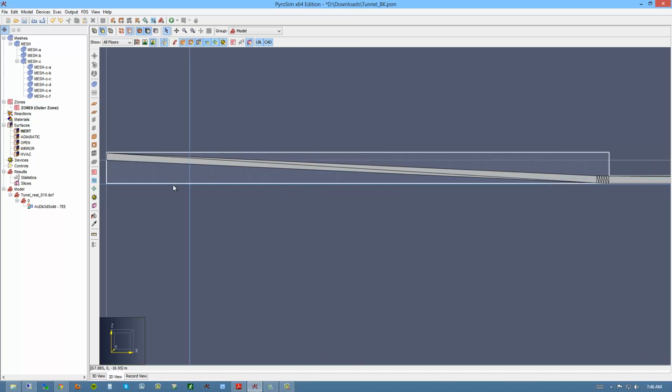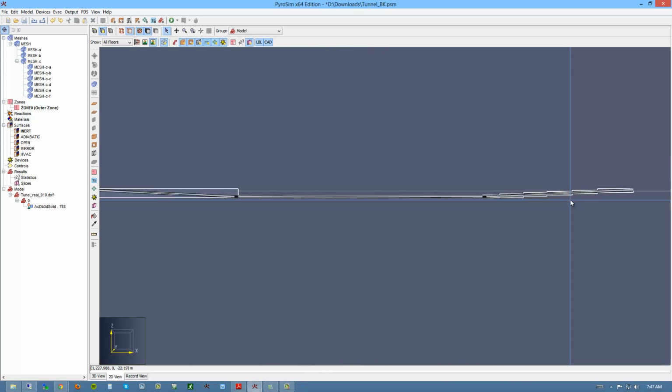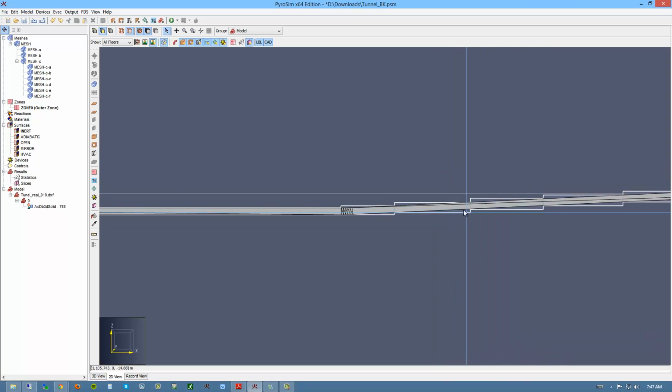So you can change the gravity vector along the x-axis so that this segment of the tunnel has a gravity vector that keeps it pointing perpendicular to the tunnel surface floor, and then this segment it would just be vertical on this normal gravity vector with z negative, and then this segment would have the vector perpendicular to the floor of this section of the tunnel.